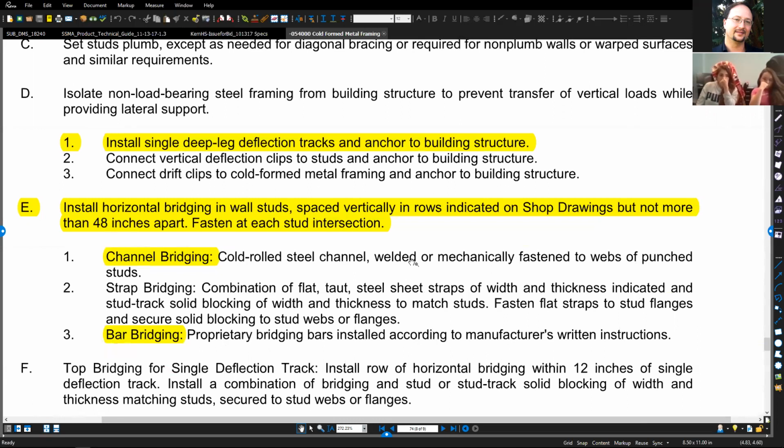It usually comes from back in the day. They called them, oh, that came from the shop. Oh, the guy's particular stuff, the shop. Oh, the shop drawings are coming in. So that's how the terminology came about: the architects got the drawings, and any other shops providing their own drawings, those are referred to as shop drawings. Shop drawings have to go in a submittal and be approved by the architect to make sure they comply with the building. And then everything gets adjusted. So shop drawings was the way everybody collaborated on the project in the past.